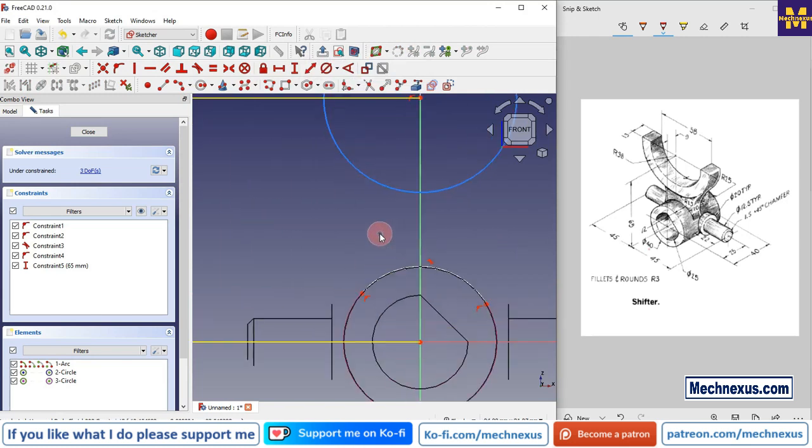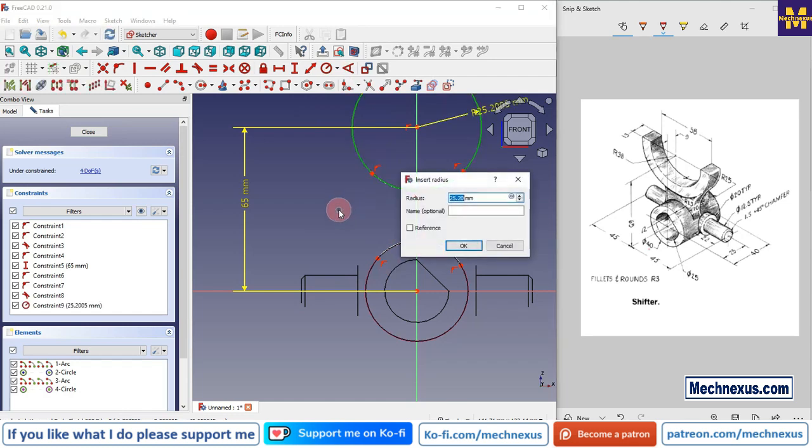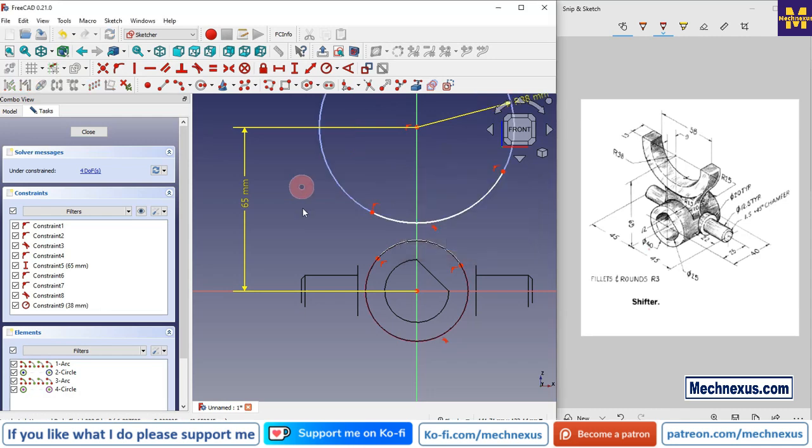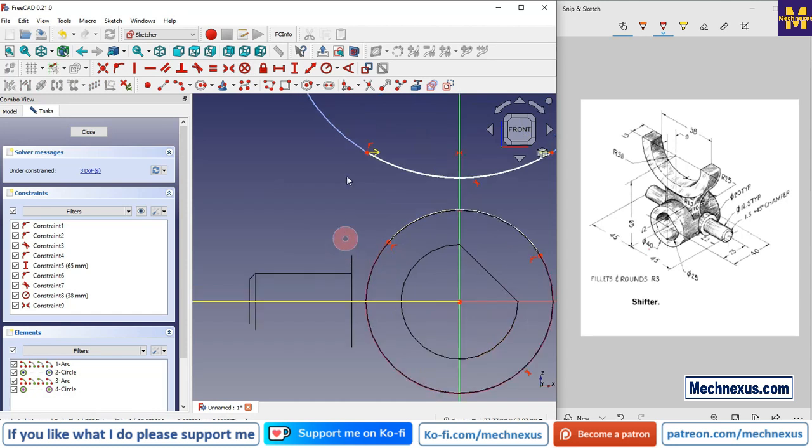So we will select these 2 points and add the dimension of 65, move it, and we will create a 3-point arc here as well, and this arc is of R38. So we will select the radius and give it 38, and now we will select these 2 points and add the symmetricity. Select this point and the axis, and we will select the 3-point arc,